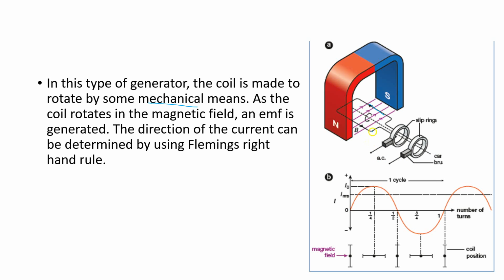But in the process of doing that, what we're essentially seeing is that if I'm turning the coil inside of the magnetic field, there will be points where the wire will be cutting against the magnetic field at a right angle. And that is what is happening here. Based on how this coil is positioned, the wire right here is placed perpendicularly to the magnetic field, so that is when it's going to experience its maximum force.